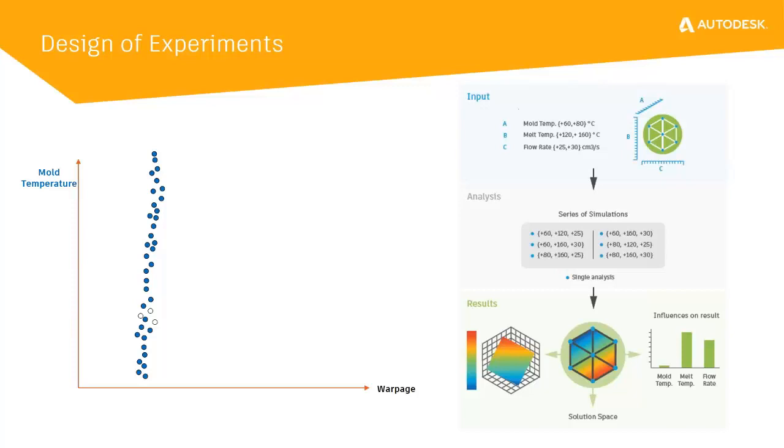I also discussed earlier how thickness variations and geometry modifications can be used in these optimization studies. From there, the user specifies which quality criteria are most important to the part. Results like cycle time or time to reach ejection temperature. Other results like sink marks, clamp force, and critical dimensions for warpage can also be specified to understand how these variables impact each quality criteria.